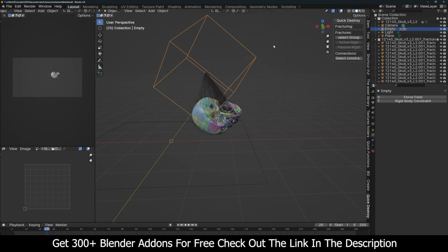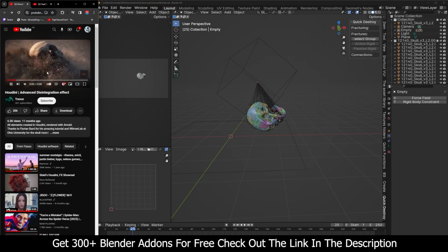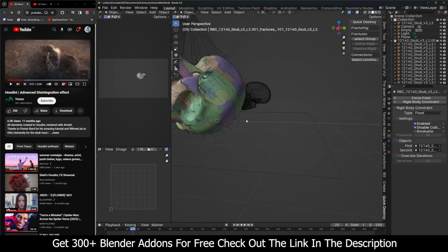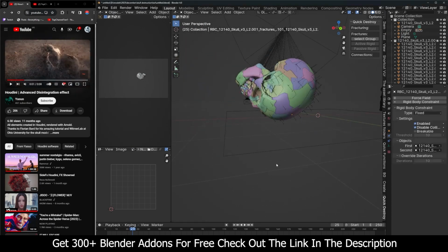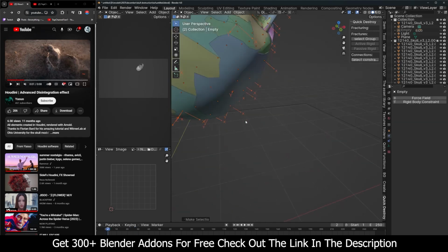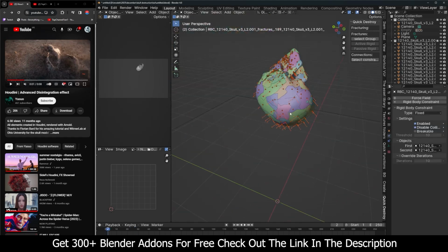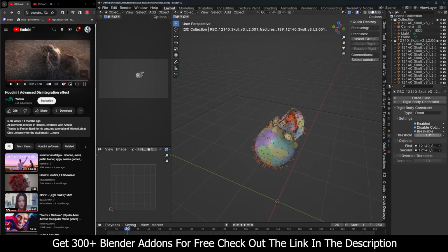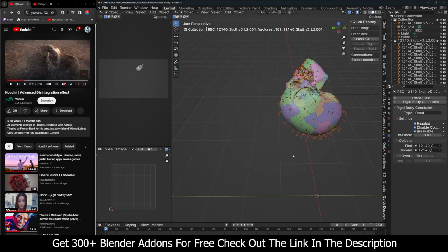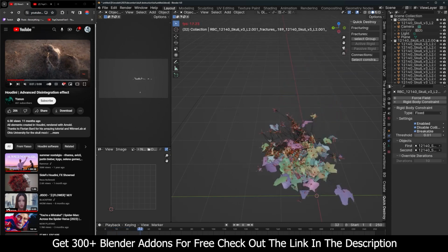Okay, so now let's try and fracture it in the same way as this. These constraints here are what controls how this is fractured. If you enable breakable, you can break them and edit the break threshold. So I'll just hold Alt and then click on breakable so that they are breakable. If we play back, they fall, but they're not breaking because the threshold is too high. If I put this at something like, let's say 0.1, hit play, now you can see everything just falls apart.